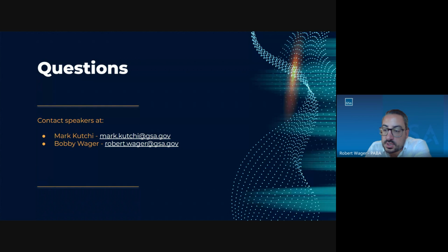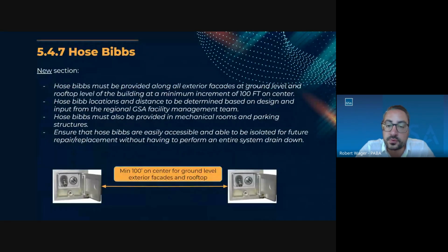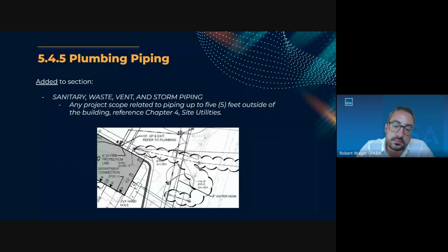Susan asks, it's unfortunate that Liebert Vertiv advertises indoor condensing units, mini-mates, 1 to 3 tons. It leads people to believe it's okay practice. Susan, I certainly agree with you. The last time I specified a Liebert unit was some time ago, but Liebert does make what's called piggyback units, and they are indoor rated units with ducted connections. So the condenser is actually inside, but you are doing the same thing in that you're ducting to the outside. So you're rejecting the heat directly outdoors, and you're not just recirculating it within the building. Hope that's clear.